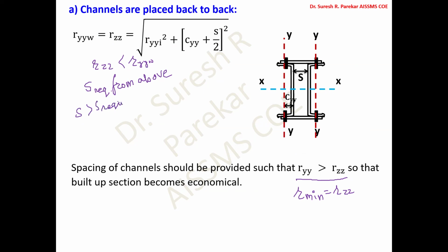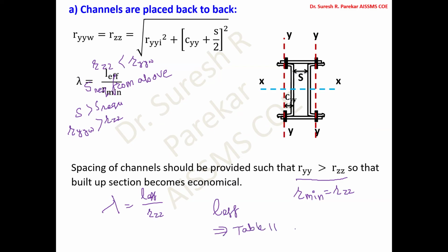If you provide S greater than S required, automatically your RYY whole is greater than RZZ, and therefore to find the value of lambda, I can directly go with RZZ. So lambda equals L effective upon RZZ. For L effective in case of these columns, we have to use table 11 given in IS 800.